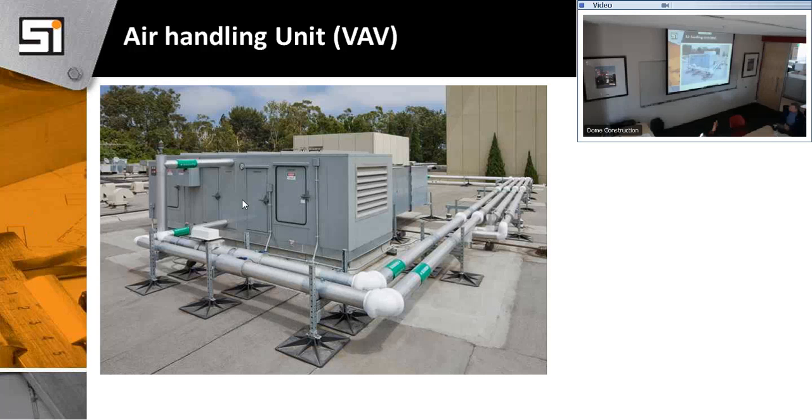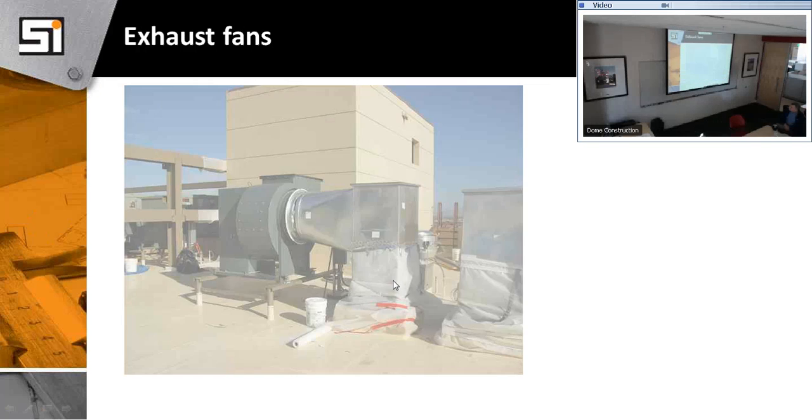But now somewhere I have a big chiller yard and a cooling tower that creates this cold. So if you're seeing this on the roof, you know that this is a chilled water air handler, and if it had two other pipes, then it'd be heating also. Those will always be labeled. You guys can walk up to a roof and see heat hot water supply return, cooling water supply return. There's labels everywhere. What is it, 10 feet or I think it's 20 feet, and change of direction.